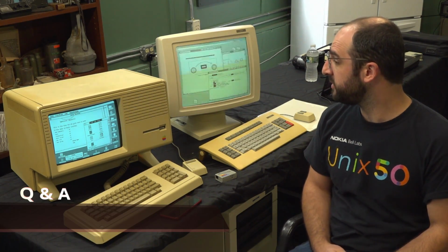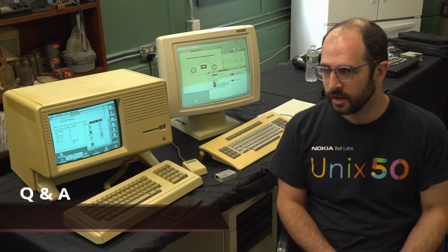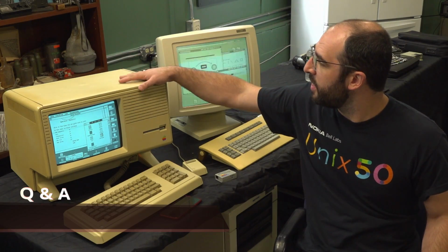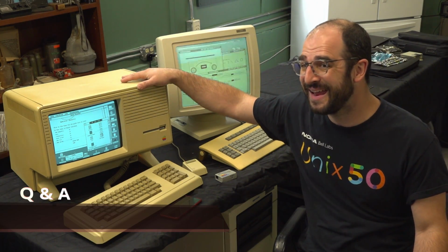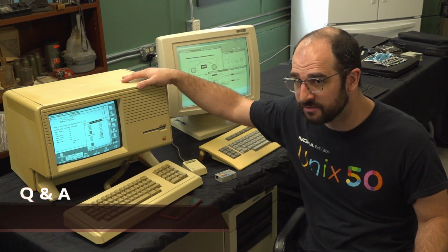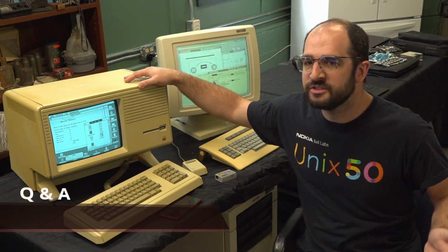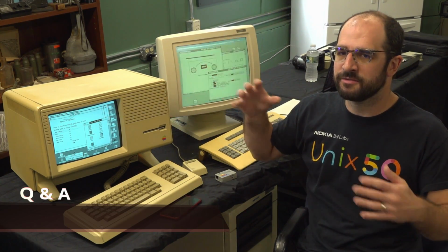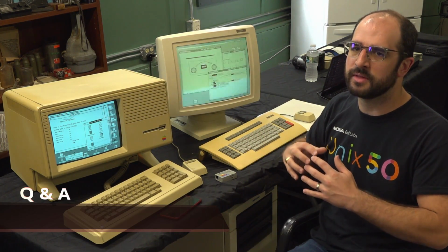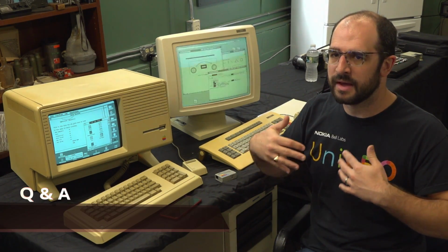The issue is that with both of these systems, the software is still pretty close to the metal, right? For example, this machine, the Lisa, has an 8 megahertz rated chip in it. The 68000 is rated 8 megahertz, but it only runs at 5 for various reasons during development. But you can't easily speed that up in the Lisa Office system because that 5 megahertz clock is also what drives the video and the floppy access. So all these things are interrelated, and you can't speed up one part of it without having issues.